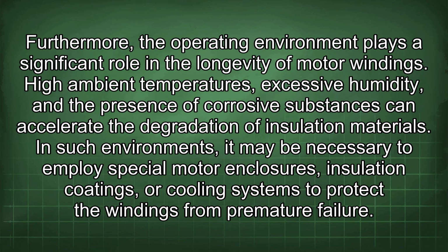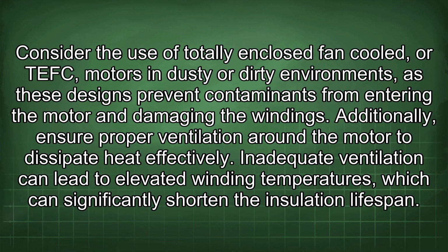In such environments, it may be necessary to employ special motor enclosures, insulation coatings, or cooling systems to protect the windings from premature failure. Consider the use of totally enclosed fan-cooled, or TEFC, motors in dusty or dirty environments, as these designs prevent contaminants from entering the motor and damaging the windings.